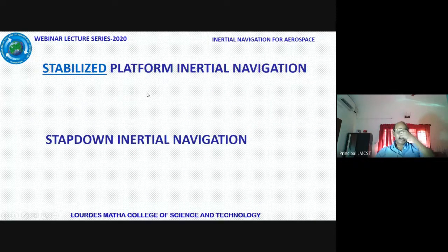So we said that our main topic of study is strap-down inertial navigation. This is the modern method of inertial navigation. Strap-down means tying the sensors onto the body or vehicle along the desired axis, so that the measurement is done in those body axes.